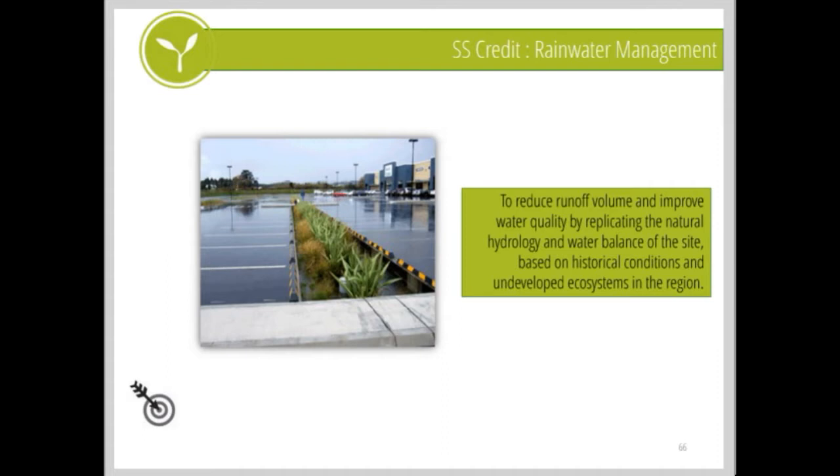Conventional site development disrupts natural hydrological systems and watersheds through impervious area, soil compaction, loss of vegetation, and loss of natural drainage patterns. The cumulative effect of these changes is a disruption to the natural water balance and water flow. Typically, a conventional site's rainwater management technique is to address the runoff by piping and conveying it as quickly as possible into large, centralized facilities at the base of drainage areas.